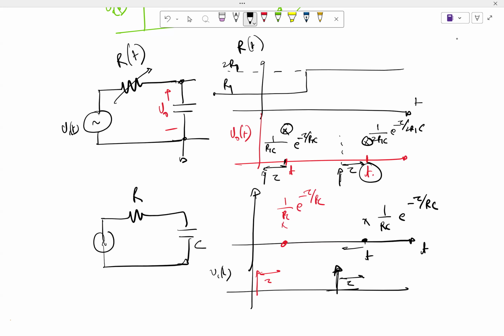So it becomes a two-variable system. An LTI system is a single variable system, where we only have to keep track of the difference of the application time and the observation time. In an LTV system, you have to keep track of where you are observing also, on top of the difference between the observation and the application. Correct? So that is another fundamental difference between LTI and LTV.